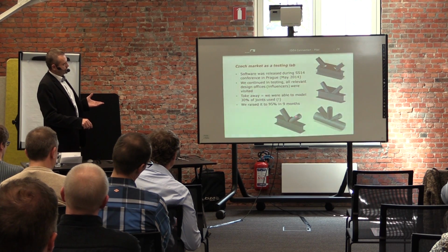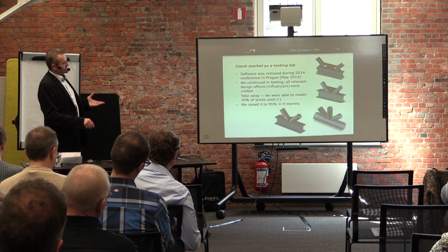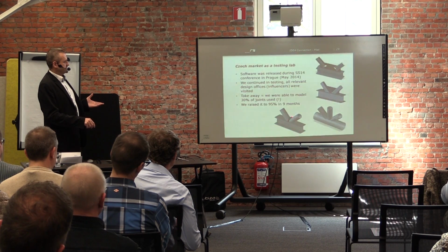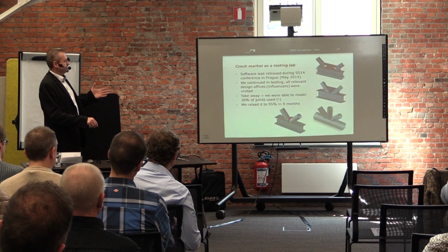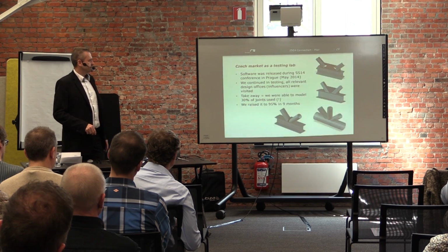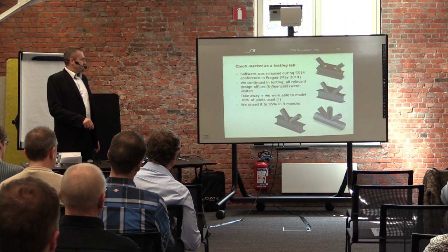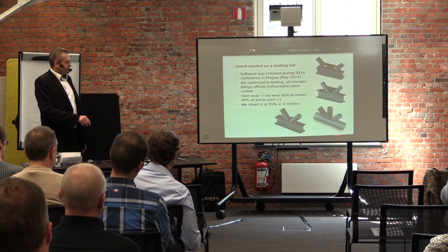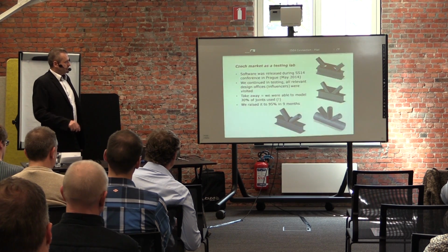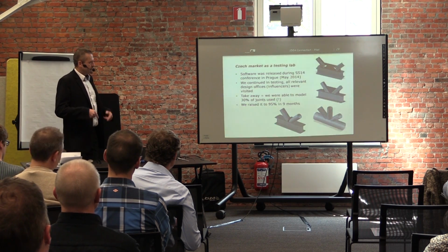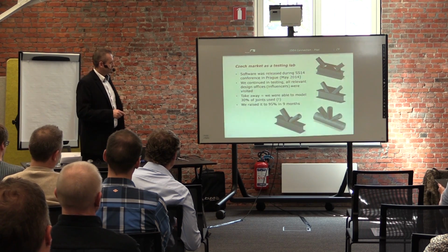This one is quite nice to put between these two hollow sections. Put in fact such a rib. It stiffens the flange quite nicely and helps these connections. And finally, we also have now the tube elements, circular hollow sections with all intersections.